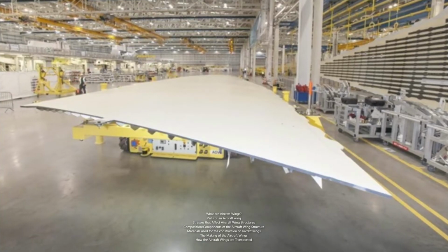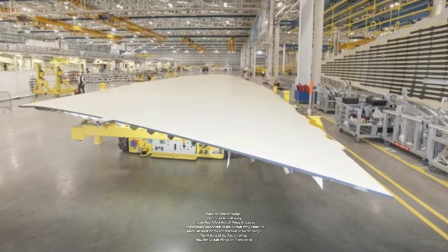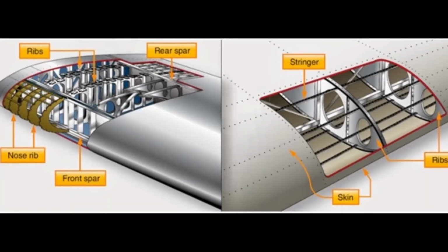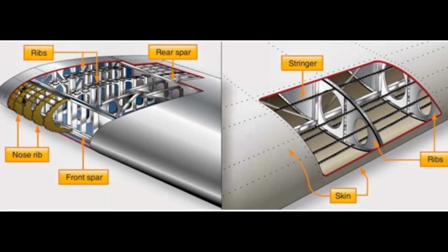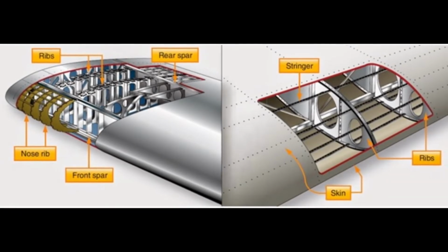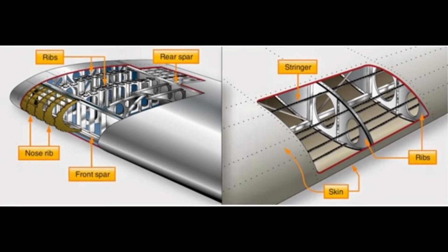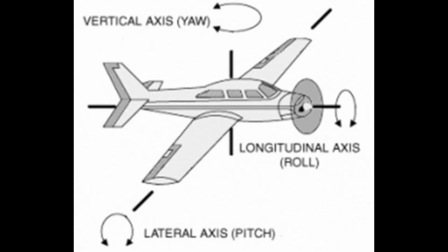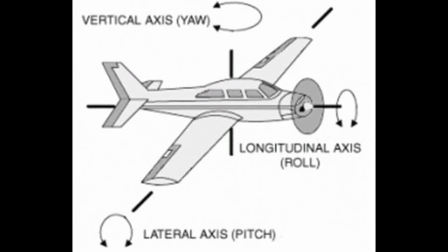Conversely, when the aircraft is on the ground, the wing tends to bend downwards, so there is tension at the top and compression at the bottom. The gravitational pull on the wing is responsible for the downward bend. During turbulence, both compression and tension stresses can be experienced by the top and bottom skin parts. The wing structure also experiences some torsional, twisting, and shearing stresses during flight. The wing needs to be able to withstand all these stresses.